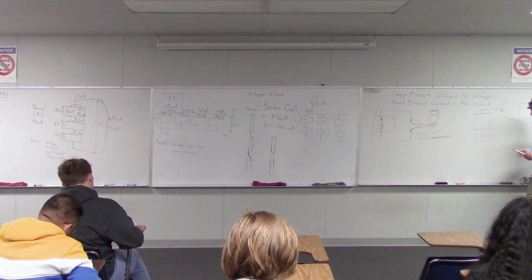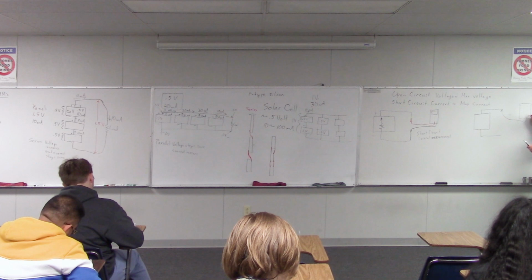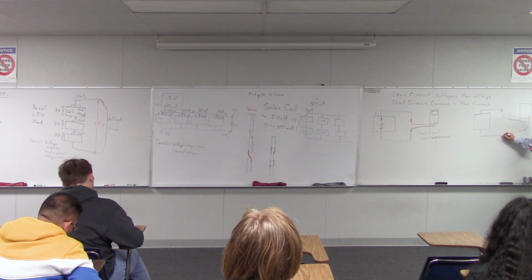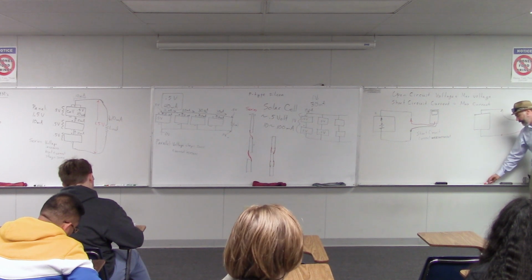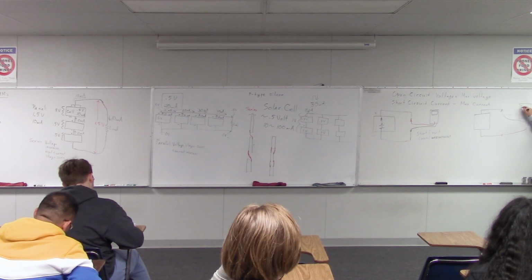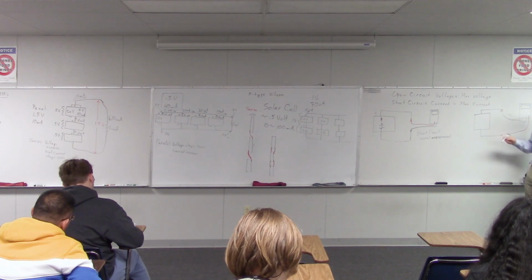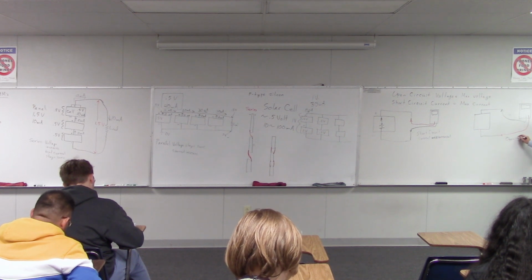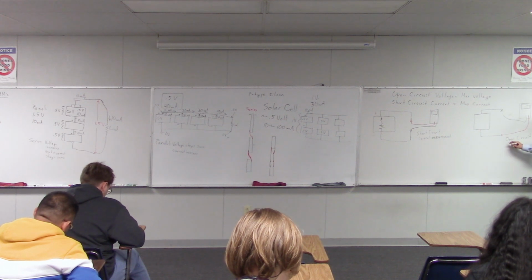So in this case, we'd connect the meter to the two ends of the panel. Does that look familiar? Same connections that we had in the last one, right? The only difference is that in this case, the meter is in voltage measuring mode, and before it was in current measuring mode. So this is the open circuit voltage measurement.